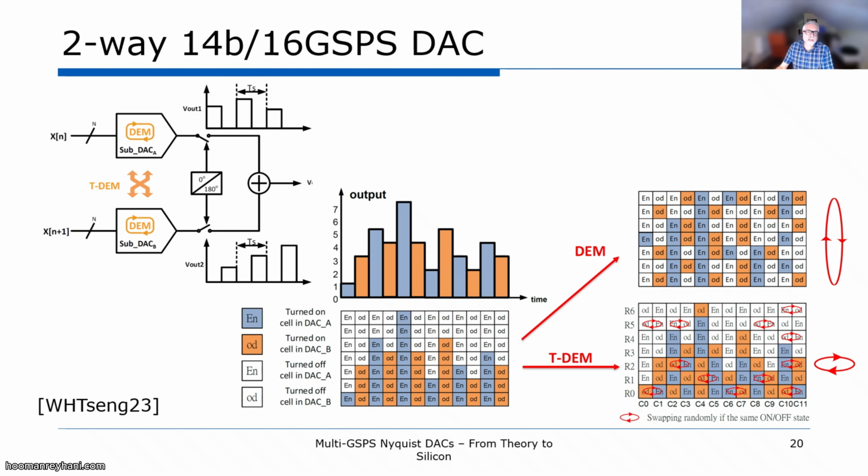Interleaving spectral artifacts are essentially spurious images of the converted signal, originating from mismatches among the interleaved DACs. Therefore, some of the techniques required to mitigate them find inspiration from traditional DAC mismatch mitigation methods, while other approaches are quite specific to the different nature of these problems.